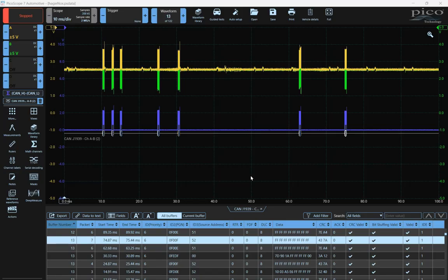I don't know the exact time for that message, the rate of it. We could easily watch it and disconnect it and see how long it takes for the ECU to set a fault for it. But it's probably going to be in the order of minutes, not in the order of a second or two, like these NOx sensors. So this becomes another piece of adding to the difficulty of diagnosing CAN problems on machines.